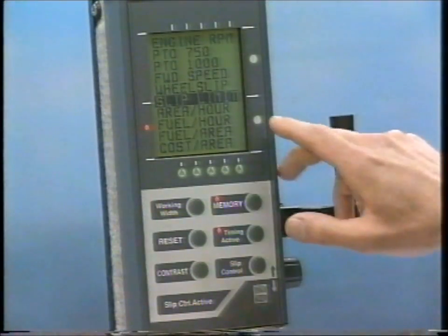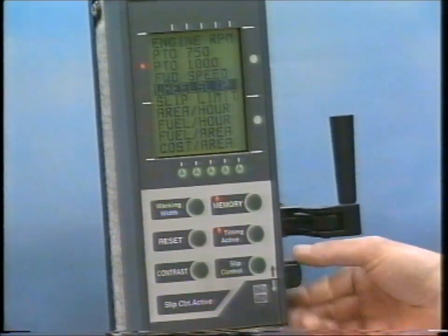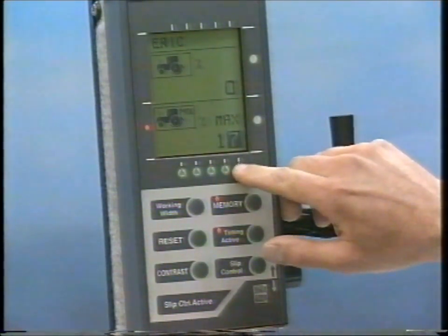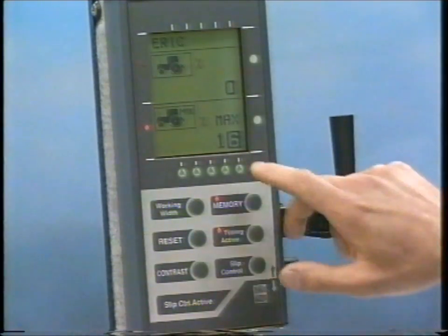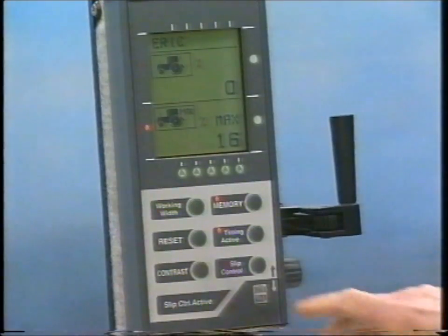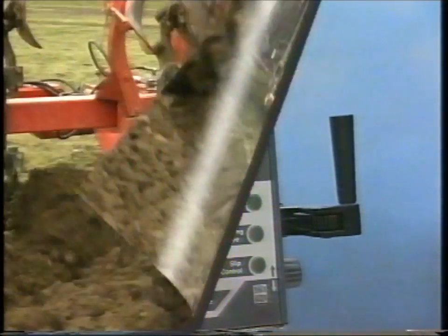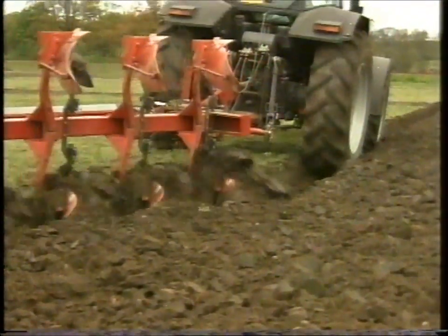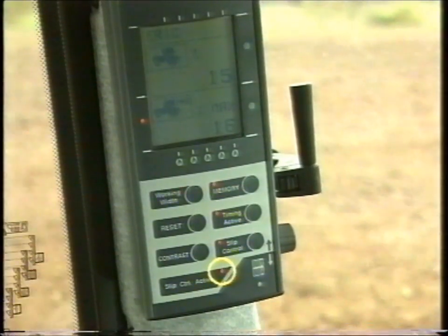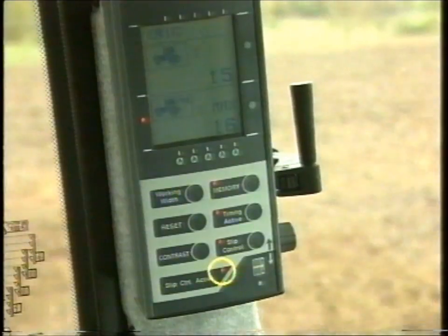To see how Datatronic II solves this problem, we return to the main menu to select Wheel Slip, which is the actual wheel slip occurring, and Slip Limit is the limit set by the operator. So, we'll now put each one into the 2 displays. At this point, the slip limit can be reset by using the green arrows and the rotary knob in increments as little as 1%.